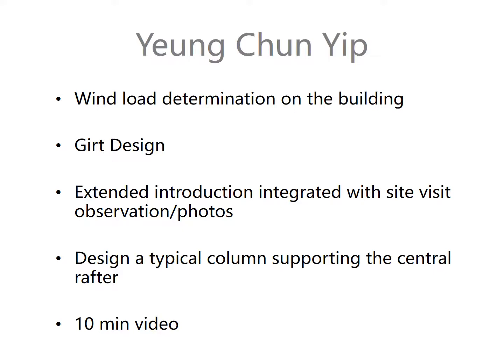Then select the topographic class, as the effect of the wind depends on the location of the house. The effect of the wind on a hill or on a ridge is different. Then select the shielding class. The shielding class can be full shielding, partial shielding, or no shielding, depending on how many houses or trees are in that area.